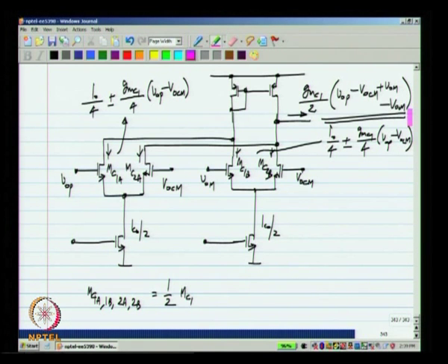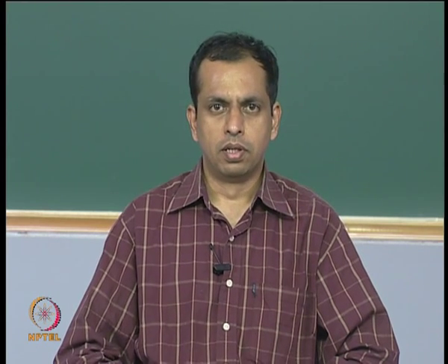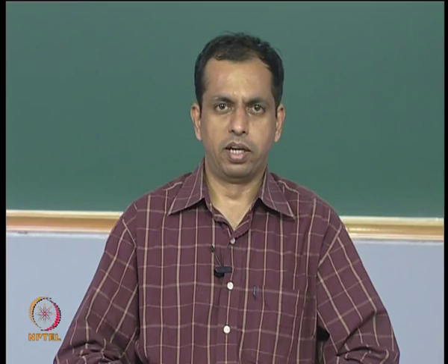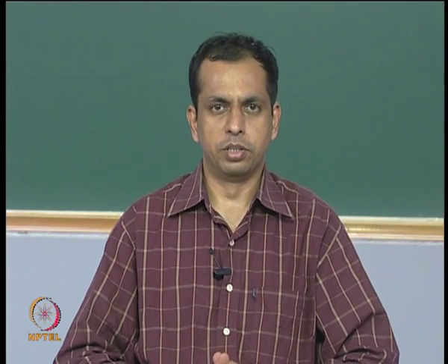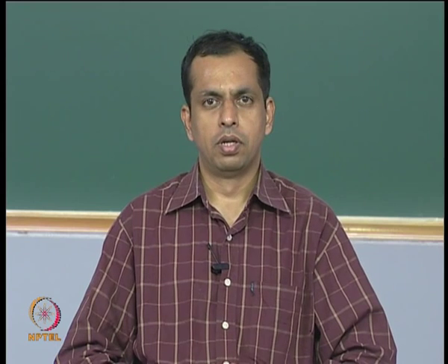Now, this is a circuit in which the common mode detection and the transconductor are merged together. What we have done is we have taken the single stage single ended op amp and split up the input transistor pair into two parts, and also made the tail current half. Basically, the differential pair is split into two halves. So, each half has half the GM as before. Okay.